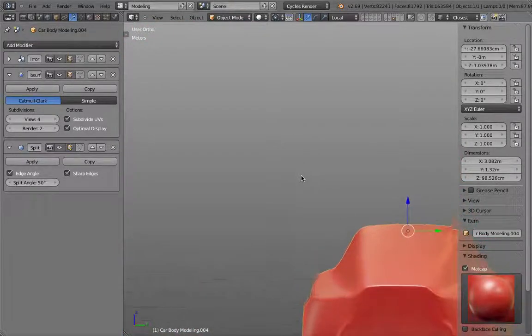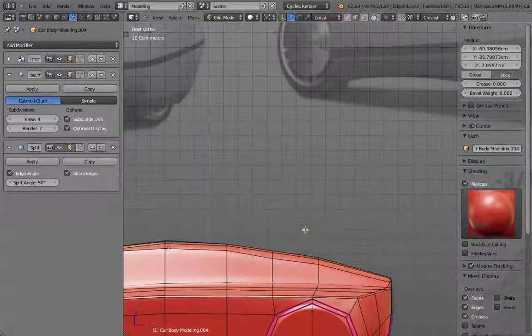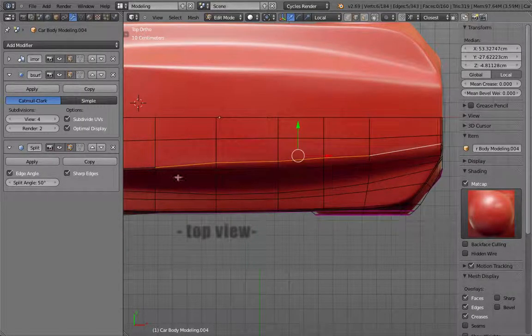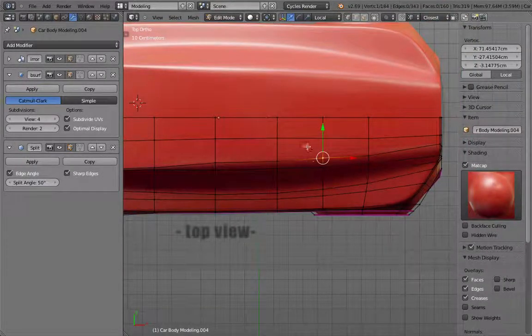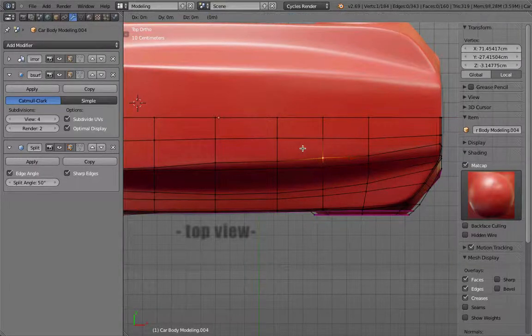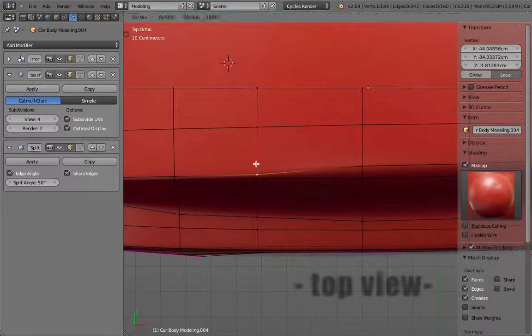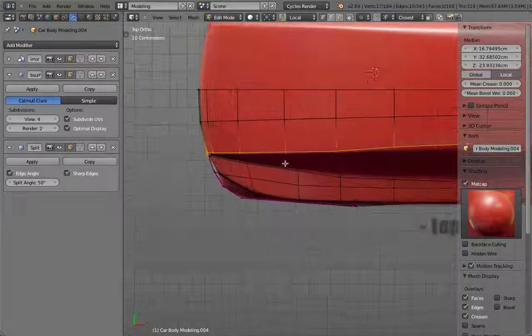And of course, then the art is just trying to, when you make those transitions, be nice and even. So for example, let's take a look in the top. You can see that, for example, this is a little bit crooked. So at this point, maybe because I want to have an arc, it has to go down a little bit. So I press GG and then try to go over this edge I need there. This one maybe can go in a little bit or upwards. So I try to see or project a curve flow through those.